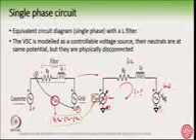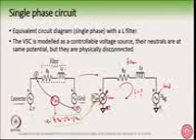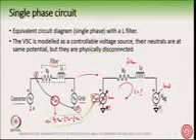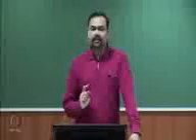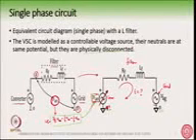You can have other types of filters also, and then there is a VAN voltage, and that is the converter's voltage, and that VAN is related to the pole voltages by this equation. The pole voltage of the converter and this VAN voltage are not the same. They are different. But this is the VAN voltage we use in the modeling, and then this is the grid voltage. It should be clearly understood.